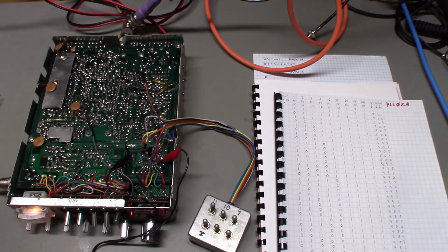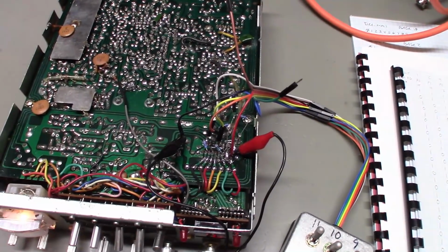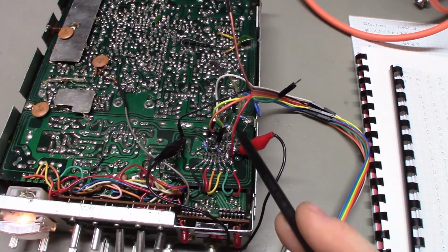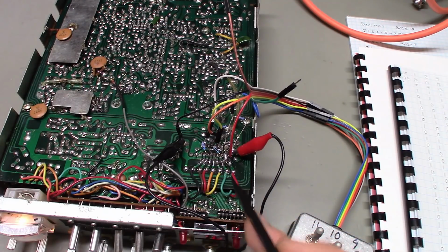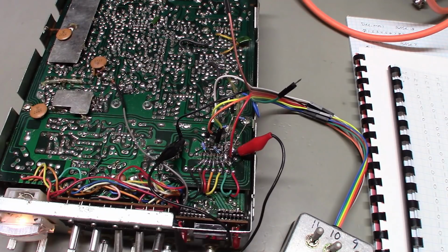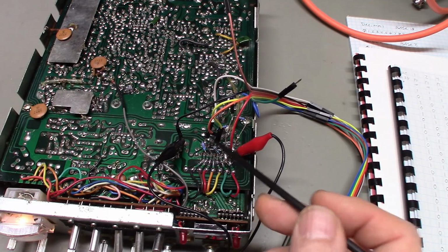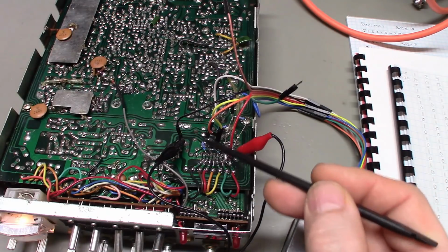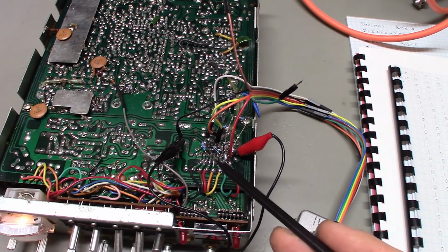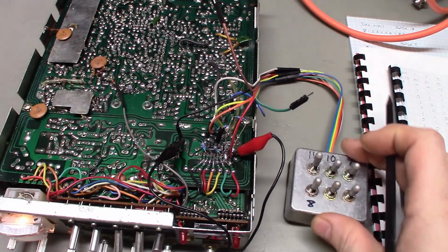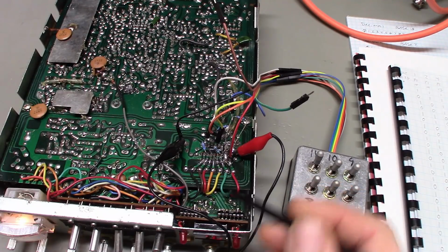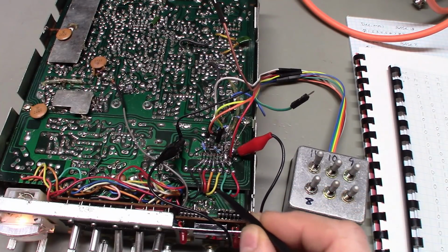But down here in the radio, you'll see that I don't actually have these wires soldered down to the pins on the circuit board. There are actually resistors that just come up over, and they're looped in and soldered down to the circuit. That's what you'll usually see in a radio. When you open it up, if it has channel modifications, you'll usually see a resistor. What that resistor is there for is, these are 3.3K or 3,300 ohm resistors. The reason they're there is, remember, you're going to be intercepting what's coming out of this pin, so out of this channel selector switch. So let's say this yellow wire right here.